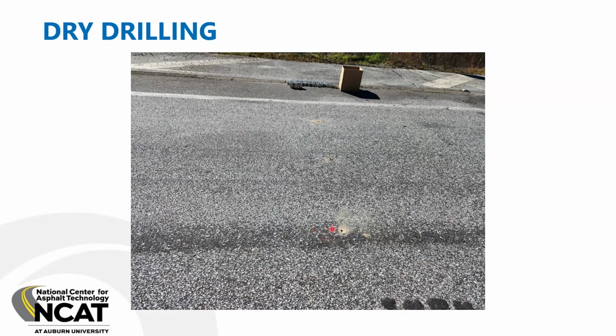But you want to make sure you still seal these holes back. So a high quality caulk or maybe a roofing cement. We're using a crack sealant, off-the-shelf crack sealant, to seal these back these days. But up in the top of the picture, you can see our moisture content tins waiting to be filled so we can take those back.